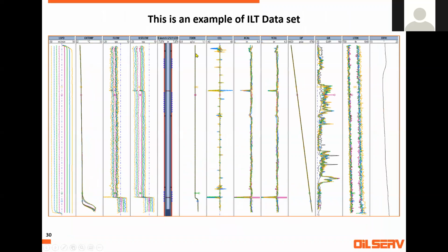Okay, this is the injector. You can see the data for the injector. This is Emeraude software. You load the data. You have line speed, you have your temperature, you have full bore spinner and line spinner data. This one I put the perf. You have your density. Everything is water, then it increases here. Why is it increased here? Because this is the dirt in the wellbore. It's called sump.